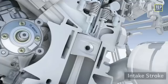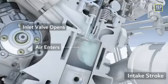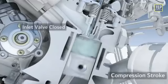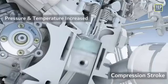Intake stroke. In the intake stroke, the piston moves down and the inlet valve is open, which allows air to enter the cylinder and fill the space. Then the piston reaches the bottom center and again starts moving up. Compression stroke. The piston starts moving up, the inlet valve is closed, and the air is compressed. The pressure and temperature of the air increase due to compression.